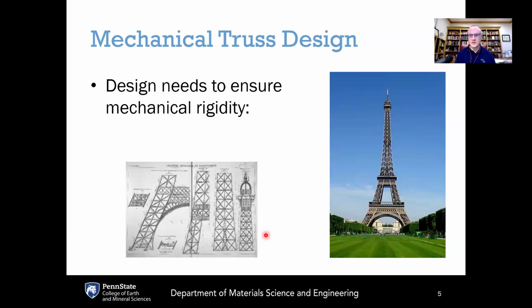This approach was actually inspired by civil engineering and architecture. If you look at most bridges and many buildings, such as the Eiffel Tower shown here, you'll note that they are not composed of squares or other types of quadrilaterals. Rather, these buildings are composed of triangles. The reason is that the triangle is a perfectly rigid object when used in architecture. If you've got three bonds connecting the three vertices of the triangle, it's not possible to deform that triangle and change the angles, because the rigid distances along all three edges are preventing you from changing the angles.